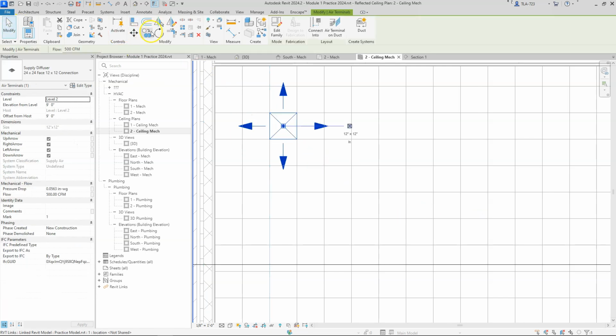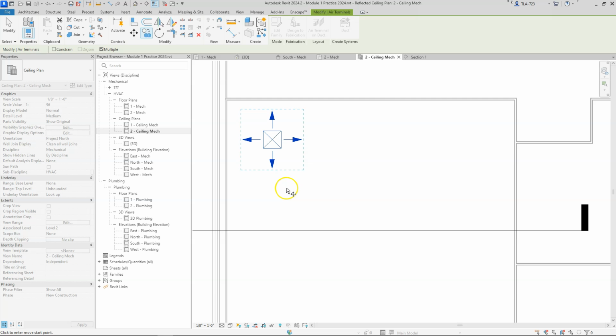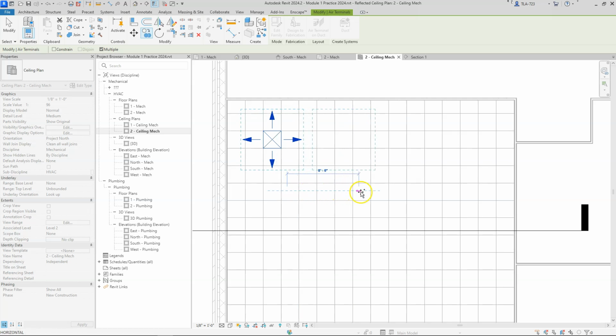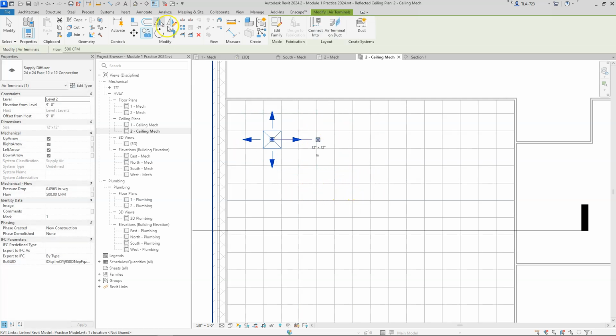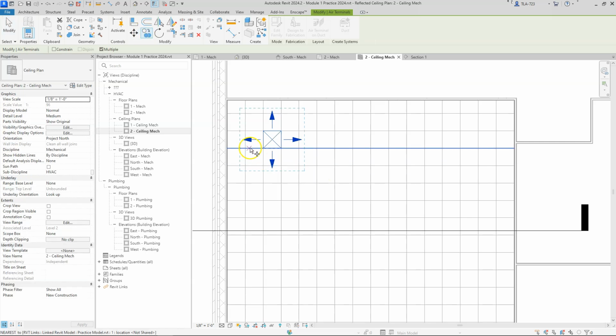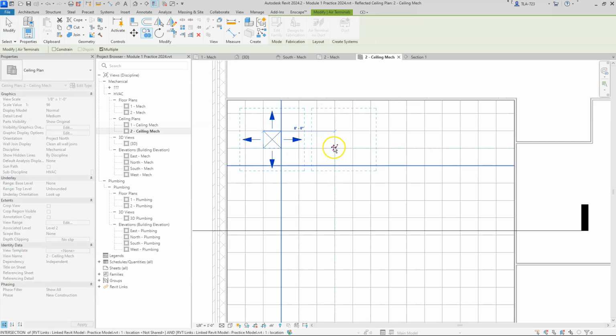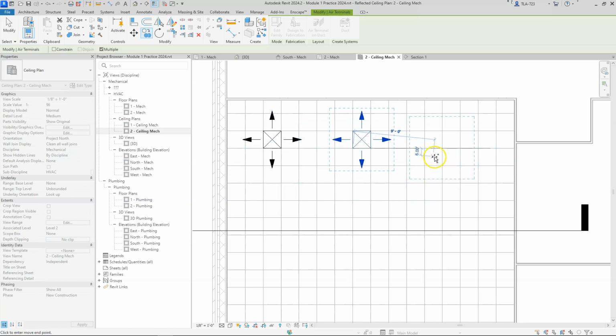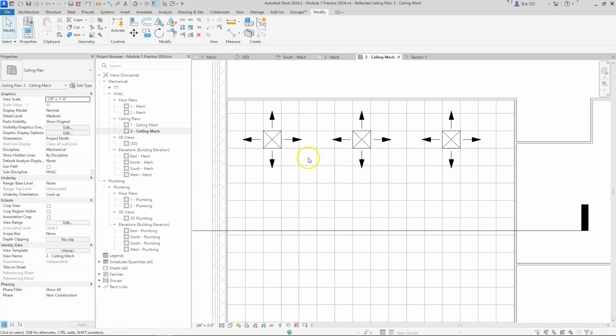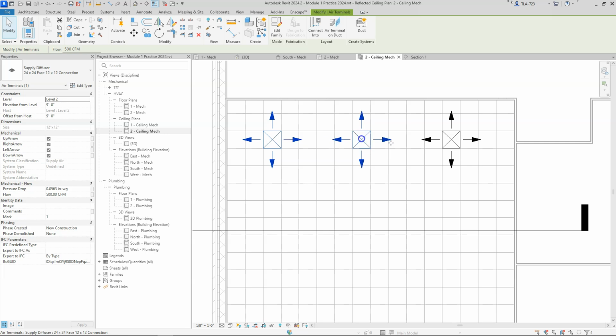So I still won't be able to easily create copies of this thing. I'm just using the copy tool. But what you could do is use object snap, and so if you pick this as your first point, then your next couple of points are going to come in also lined up with that grid system. Okay, and you could do the same thing with these 3 once you have them in there.